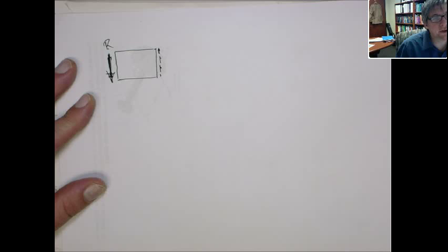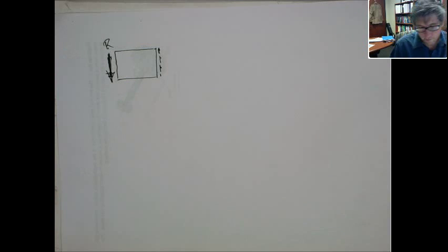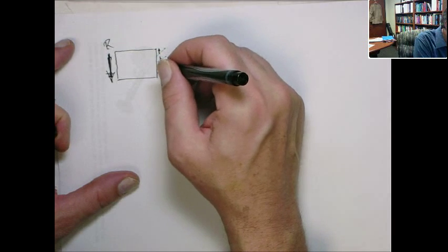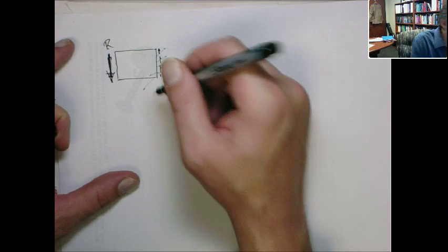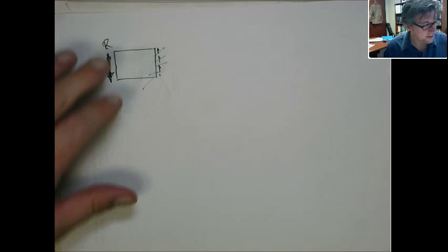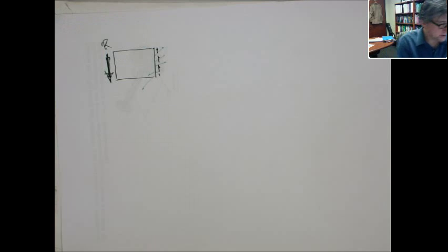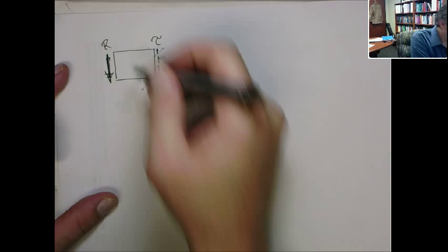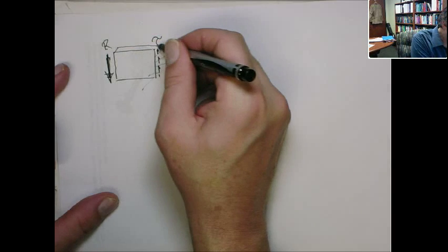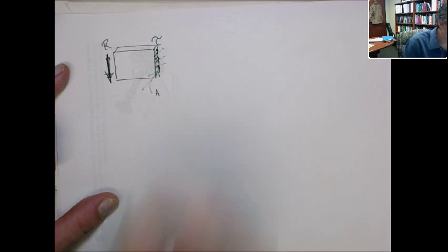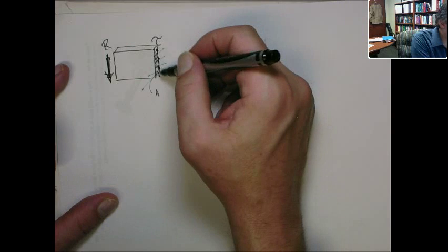There's actually some distribution of shear stresses on that base. Remember the actual traction. There's a normal, and then we're looking at the in-plane component, or the shear component. So this is actually tau as a function of position on that surface. The surface we're talking about is this surface here. This is A.